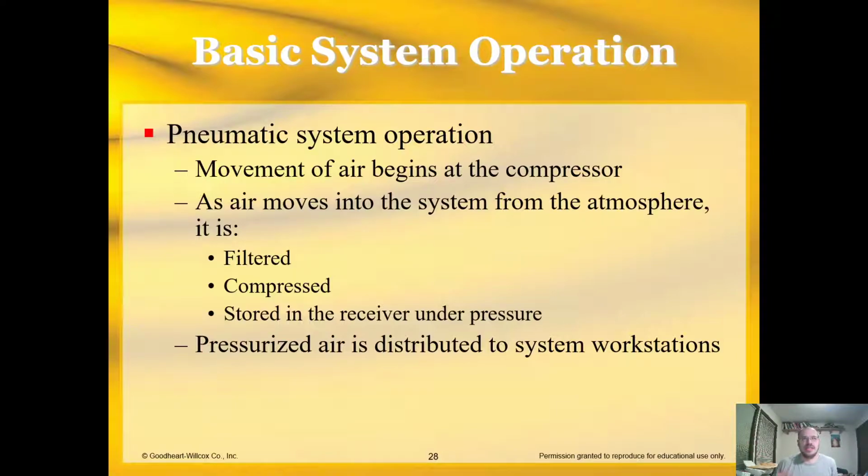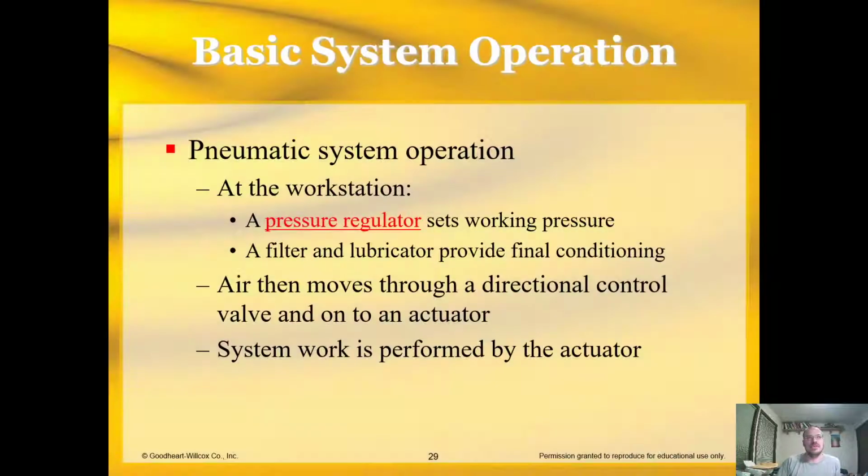So that air is pressurized, brought up to the pressure that you've set your compressor at. And then the pressurized air is distributed to the system workstation. So where are you doing the work, right? To your machine or device that you're using.